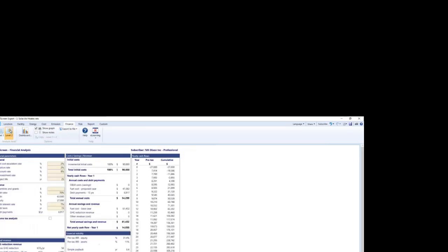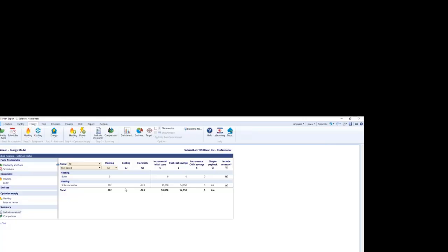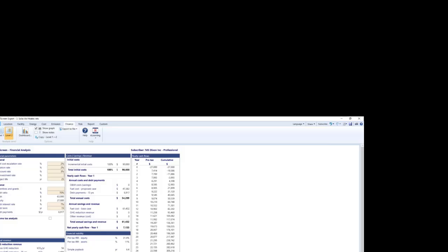And we can go so far as to do a much more detailed analysis as well, where we consider discounting. So if in a hospital you might have a discount rate or weighted cost of capital for projects of 3%, we can then calculate things like the benefit to cost ratio. Over the 25-year life of this system, the benefit to cost ratio is 8.4. What that means is you're going to get 8 times as much money back as you put into it. So even though this thing required an investment of around $90,000, if we take a look at the financial analysis, the net present value turns out to be somewhere on the order of $200,000. So there's a very strong tool for being able to make a strong argument here.